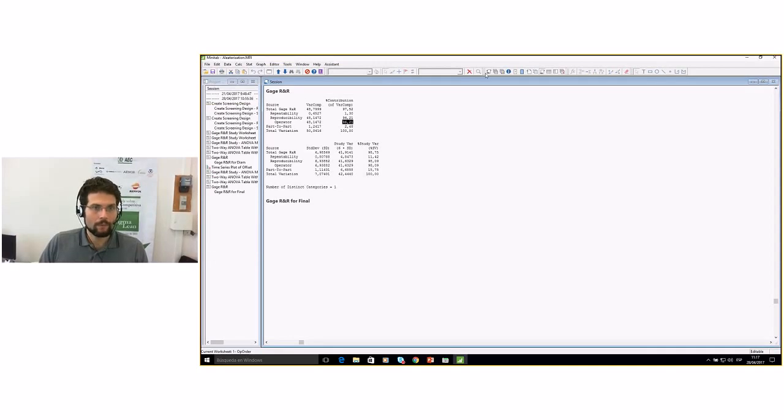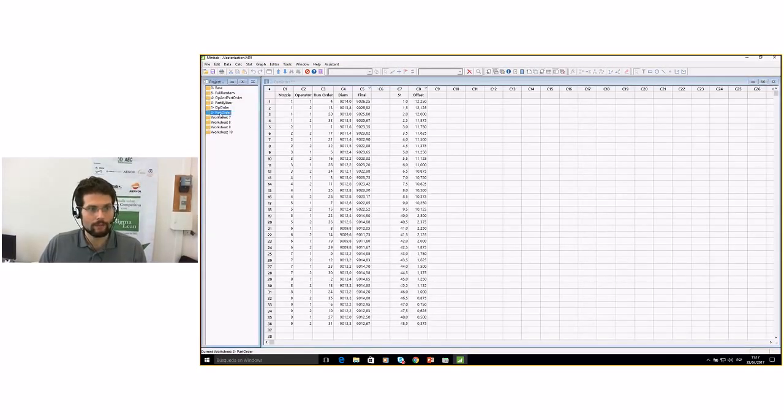So we'll have a look at a second configuration, which is measuring the parts in order. I get a first part and I don't want to move it, so I ask both operators to do their measurements. Then I get a second part and I ask another operator to do his measurements. If the parts I'm producing are heavy or take a lot of space, that could be a tendency that we would have. So I bring the first part, and ask operator 1 to measure it, then operator 2, and 1 and 2 again.